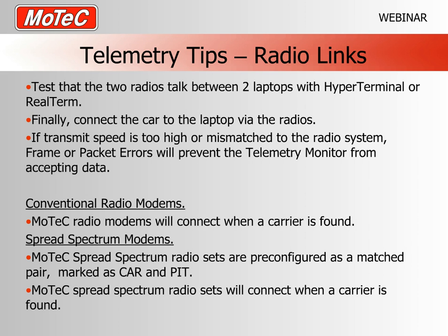So what you need to do is get two laptops, if you like, plug each laptop into one of your radios and use one of these terminal programs to just type messages, because if there's any corruption of the radio data, then you won't even be able to transmit typed messages. And once again, if your telemetry system works correctly, but the radio system is making the data fuzzy, then you're not going to see valid data in your telemetry monitor program.